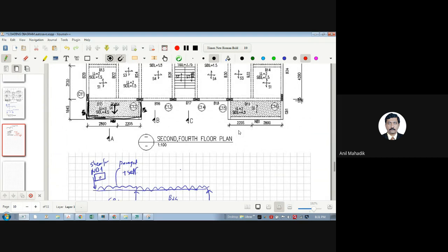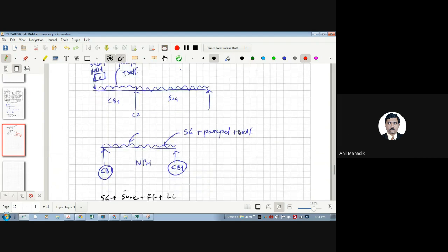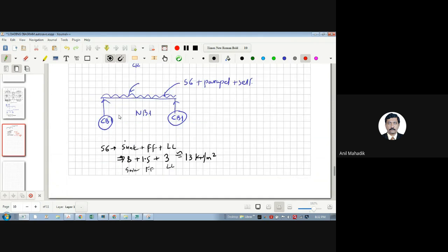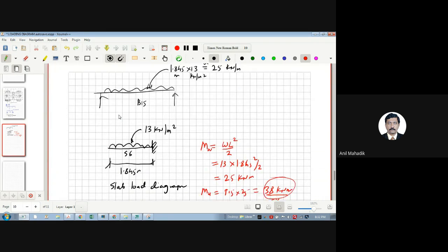And one more point, that in this case you need to assume a little more live load actually. क्या होता है बहुत बार यहाँ है ना, even though we provide say a cantilever slab without any beams, there will be some railing or glass railing or whatever. So there will be some point load here at the end. So as a matter of additional safety, because people put some load, you can take some point load here also of parapet wall.